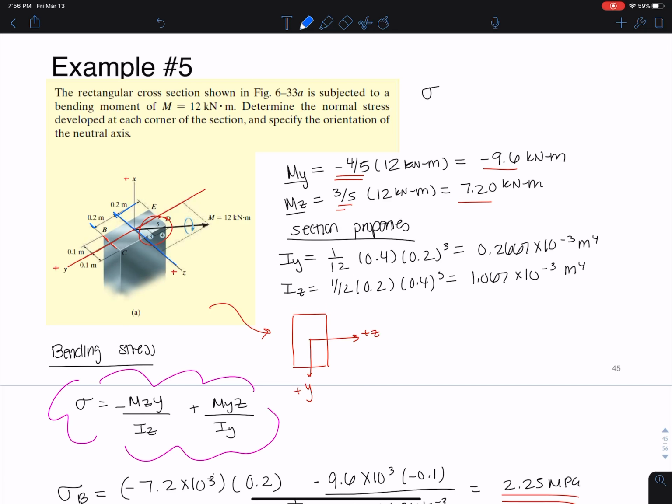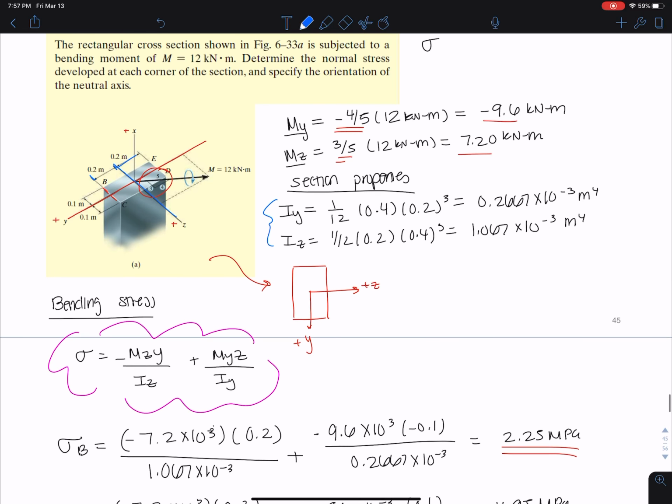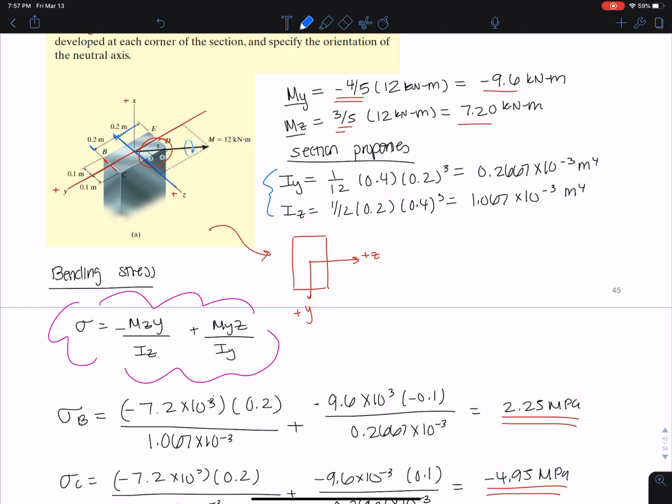Okay, so this is a good couple of calculations to practice. Make sure you understand that moment of inertia is not just a geometry for any cross section. It's highly dependent on the axis that you're taking the moment of inertia about, and that changes it. And you can always remember this as its resistance to rotation, and rotation is applied about an axis. So that means moment of inertia has to be dependent on the axis that you are calculating it about. Okay, so this is a good reminder to help you remember that, okay?